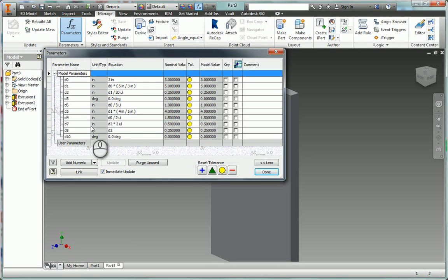And then when I extrude something, I have a D10, which is a degree there. Let's see, we don't want that. Let's call that D9, because it skipped D9 on me, it looks like. So I'm going to change that to D9. Okay, good. So now I'll be able to start with my D10.